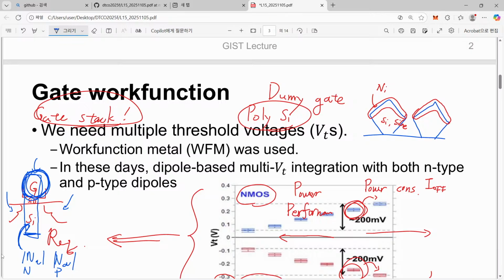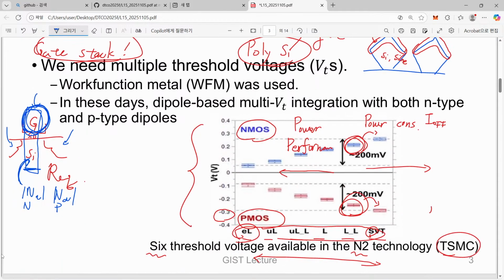That was the situation. However, historically there was a big problem obtained from this trend. People always reduce this silicon dioxide thickness, so effective oxide thickness was getting shorter and shorter, and now the gate was quite powerful, so it can easily turn on our transistor.